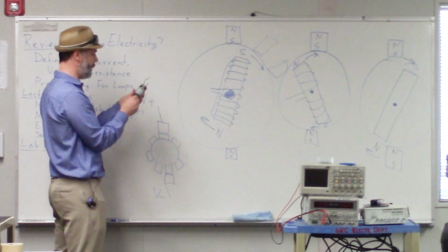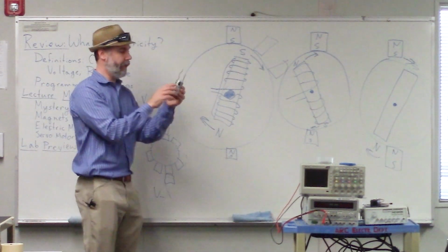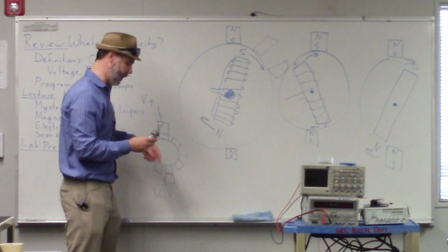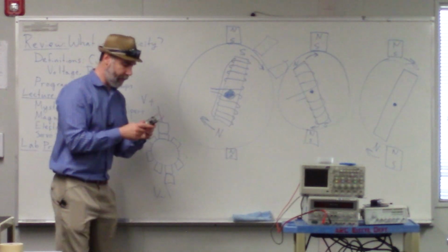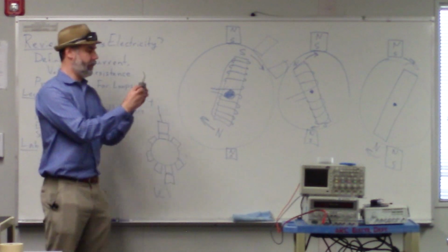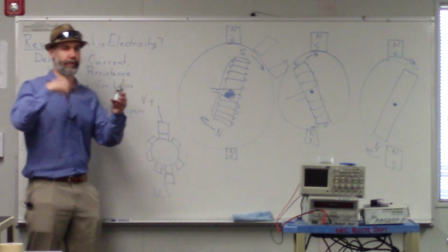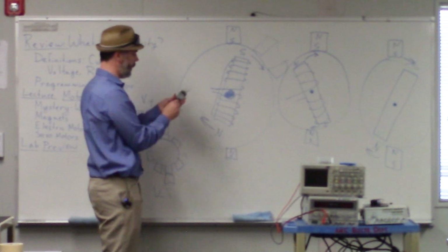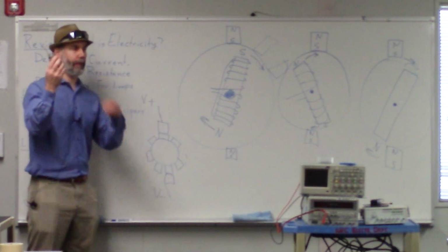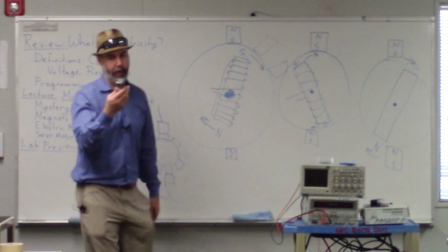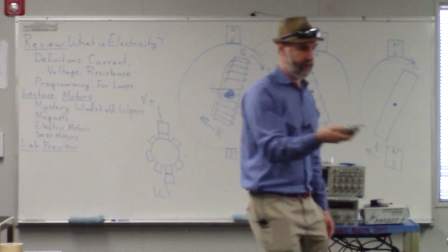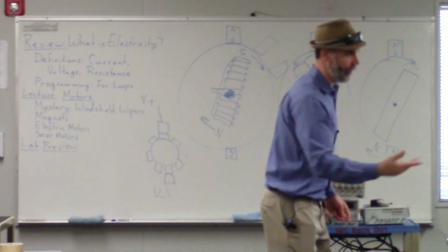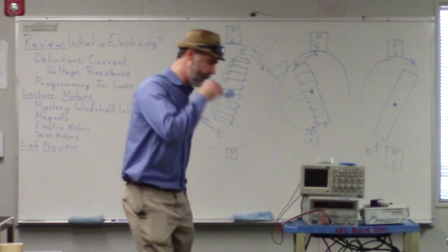You can see where those graphite brushes are actually touching the electrical connections. And then down below, you can see electrical windings, coils and coils of wire. Those are the electromagnets that are around the shaft of this motor. This is a motor that came out of a weed whacker, so it's a pretty common thing. But you can really see what's going on inside there.